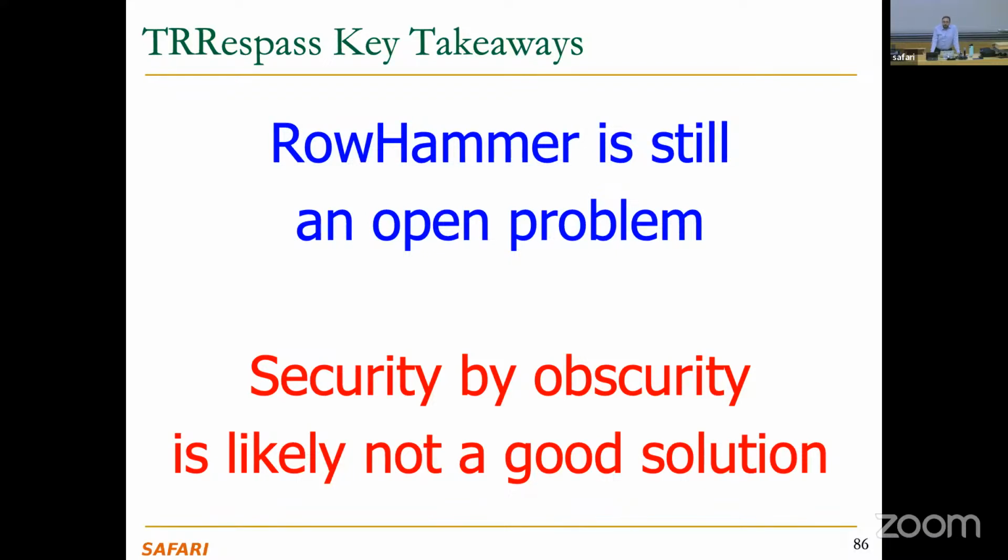So there are several sensitivities of this phenomenon. One of them is data pattern. So usually you put your data pattern in your aggressor row in such a way that you can guide where the bit flip will occur. It's not guaranteed, of course, because it's some unreliable behavior in the system anyway, right? But if you insist a lot and if you put a lot of effort, you can actually do that.